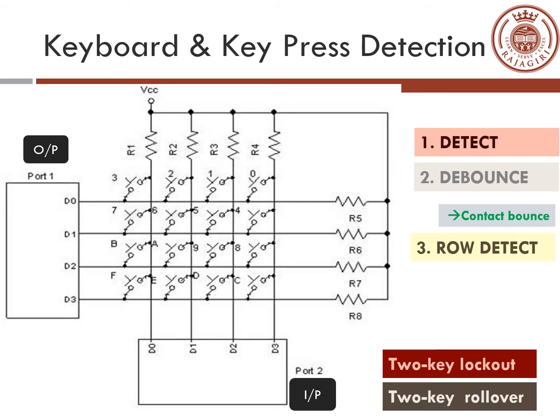The main functions of the keyboard are to detect the key that is pressed and store the value determining which key it is. The second function is called a debounce. When the key, which is a mechanical switch, is pressed, a phenomenon called contact bounce happens, whereby it appears as if the switch is pressed more than once until it reaches a steady value.